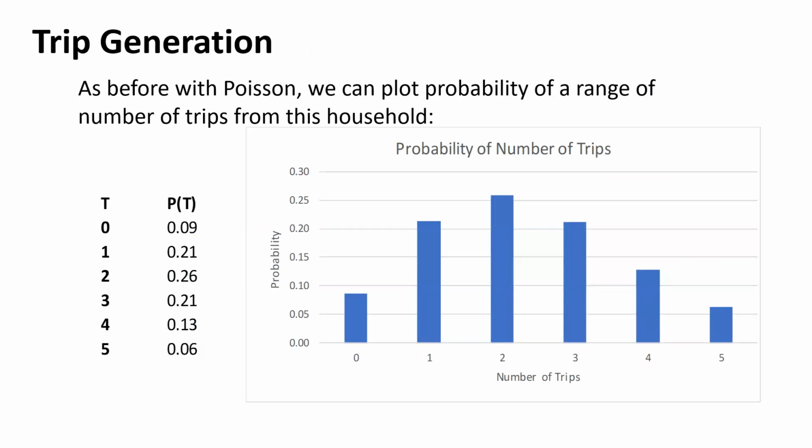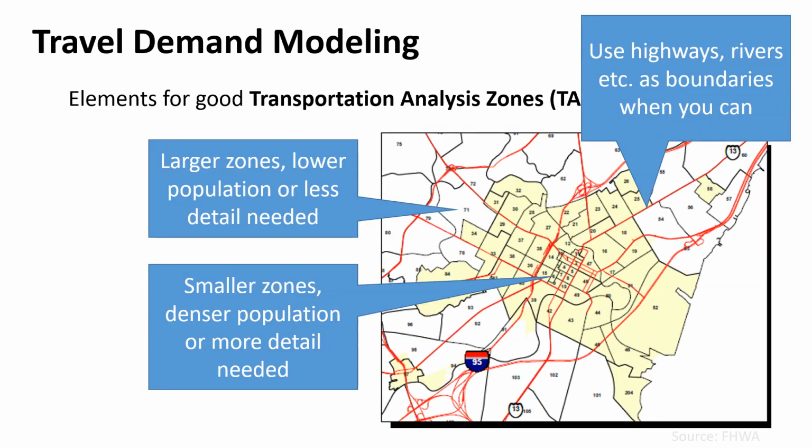And before, when we were talking about trip generation, to plug these trip generation values in, we want to apply this to an entire zone, to an analysis zone, and keeping these things homogeneous is going to be helpful for doing that. Right, so we can model the number of trips coming out of here better. And if we know that one of these zones has a lot of office space and a lot of employment for office, it's easier to model how many trips are going to go there because it's more homogeneous, right? It's the larger attractor in that sense.